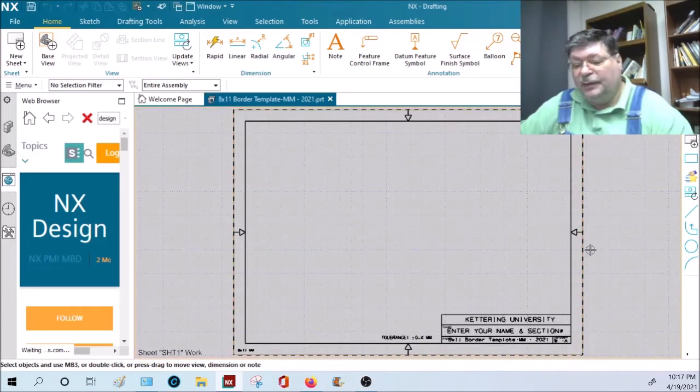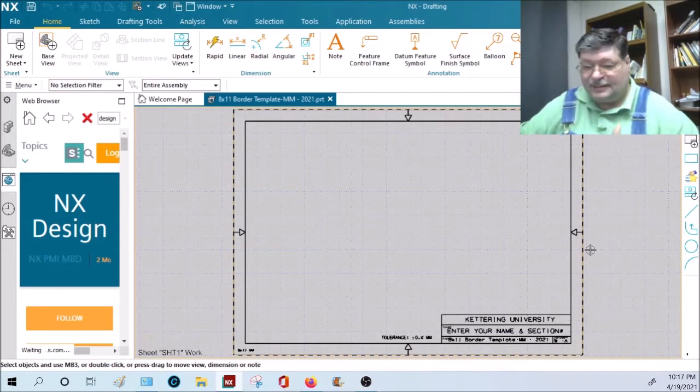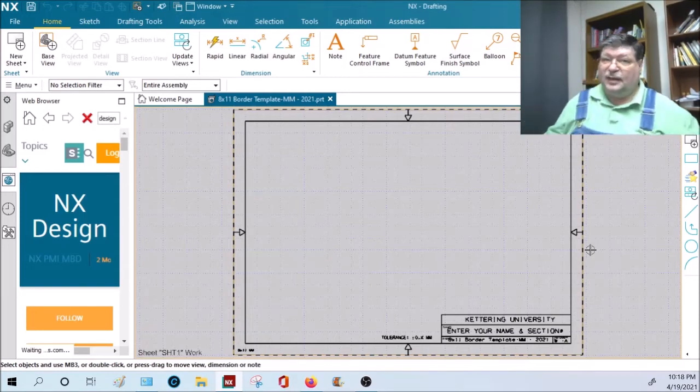If you use this one, notice the title block is a lot smaller. The defaults that we need for this class, the text size and stuff, I actually minimized a little bit, a little bit smaller than standard sizes, because no one uses 8.5 by 11 pieces of paper in industry. The smallest you'll see CAD drawings in industry are 11 by 17, and those are usually just worksheets. They're not for documents. They fit on somebody's desk easy. But typically the smallest industry used sheet is 36 by 24, and they go up to 48 by 36.